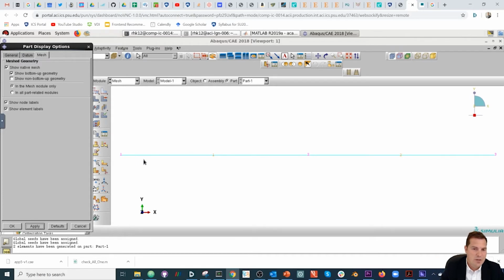But what you notice is that Abaqus is smart, and it assigned 1, 2, and 3. These node values do not correspond to ours. Basically 1 matches, but Abaqus's node 2 is our node 3, because I switched it up to make it a little more complex. So their node 3 is our node 2. We have to keep that in mind when we run this and compare to our hand calculations. We have to swap those.